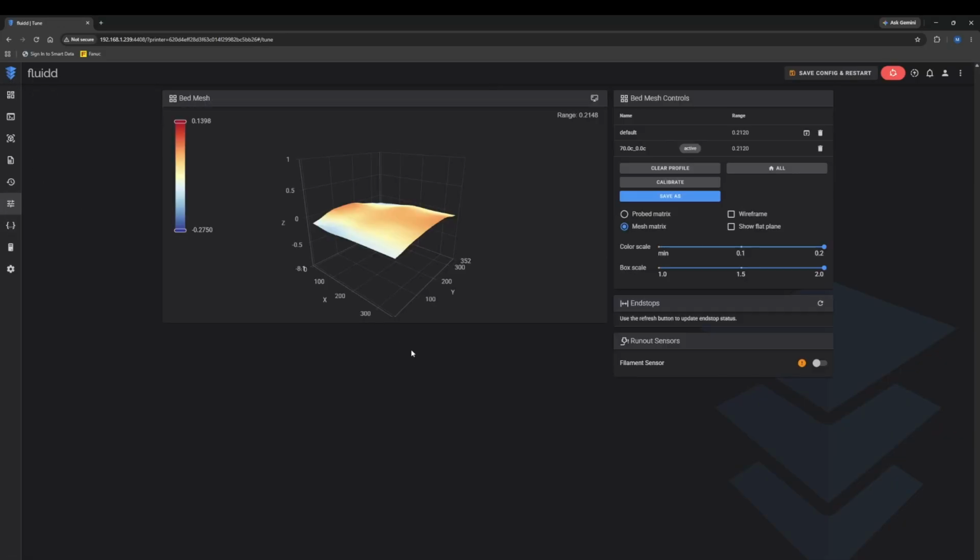The other option that we're going to install is a plate aware bed mesh. So it still uses the temperature settings to create the mesh, but now it also adds in the type of plate that you have installed on the machine to save a mesh. Plates may have different flatness, thickness, or differences of any kind.